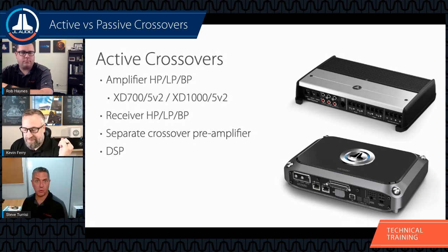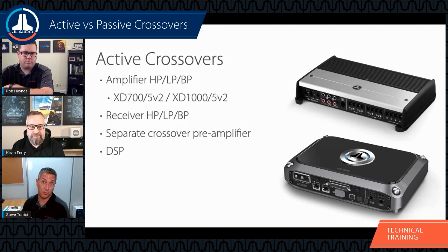Level control, yeah, I get that. Let's put some level control up in the front, for maybe your tweeters and certainly your subwoofers. But when it comes to filter frequencies, I'm with Kevin, man. Don't even bother using the one that's in the source unit. It may be good, it may not be good, but the one in the amplifier, you can dial it in pretty well, especially if you're dealing with a DSP. Let's use the tools in an area that's probably the safest and smartest.